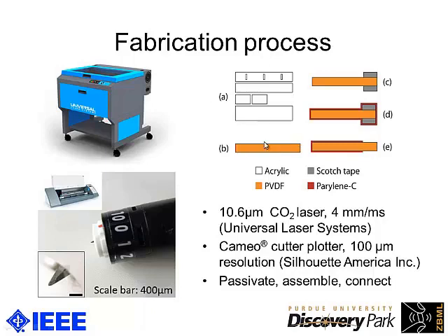The PVDF, that one's usually tricky to work with, especially with traditional cleanroom technology, because it's very sensitive to temperature and other processing techniques. But we can process it mechanically by using the cutter plotter. We can see a cutter plotter basically takes a blade, runs it along the material, and traces out a computer-generated design to cut out the strips.